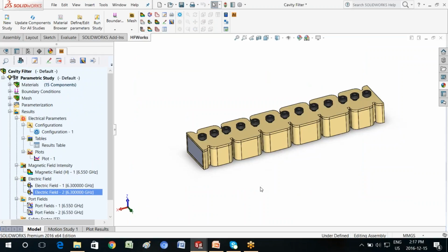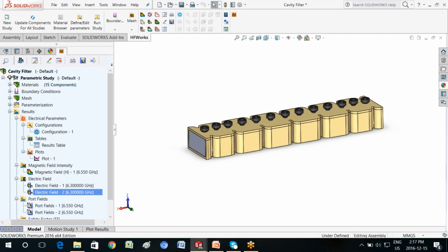Okay. Now we have a cavity filter that's made up of at least 6 of these kinds of cells, and you have screws that can go up and down, and this is the problem that we are really interested in. The first starting point we used to compute the resonant frequency gives us an idea about where this filter is going to operate. I know this beforehand, but it's between 6 and 7 gigahertz where this filter operates at its best.